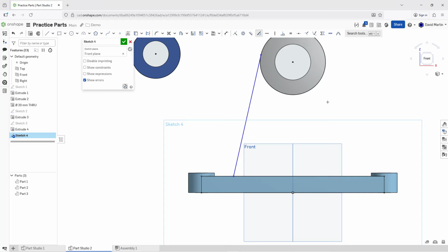This line needs to be over on the other side. If you take a look at the drawing, there is a 180 dimension at the bottom for the distance between the vertices. So let's mirror. I will go to the mirror command. Oh, that's symmetric. Where the heck is mirror? It's over here. Mirror, and I will mirror about this entity, and I will mirror this line. Let's create our dimension. I will dimension from the left vertex to the right vertex. You can pick them in any order. And I have almost the exact value that I want. This needs to be a value of 180, enter.